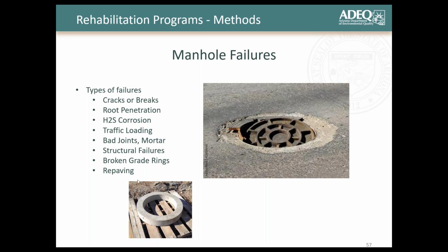So a lot of failures happen because of repaving. A very common job for us to do is raise and recover manholes after they got paved, right? Because if they weren't coordinating with the city or agency, then they'd pave right over your manhole structure, get it completely covered up. You'd have to go out, locate it, jackhammer it out, raise it up, add a couple of grade rings, make sure everything's back in operational order, accessible, right? You want to make sure that all your manholes are accessible, right?